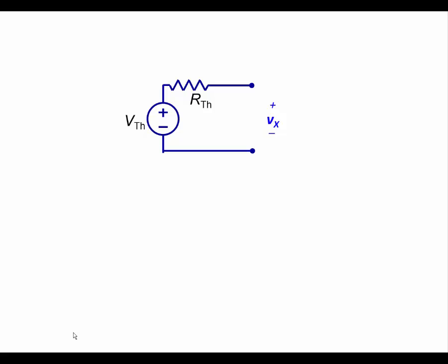Here's another way for finding R Thevenin that involves adding external resistors across the output terminals of the waveform generator. Suppose we were to take a resistor and connect it across the terminals of the BNC connector. We would need some sort of adapter or perhaps some clip leads on a coax cable to do that. When we add a second external resistor, we create a voltage divider that provides a fraction of V Thevenin at Vx. And you remember the voltage divider formula says that the voltage across this pink resistor, Vx, is going to be equal to V Thevenin